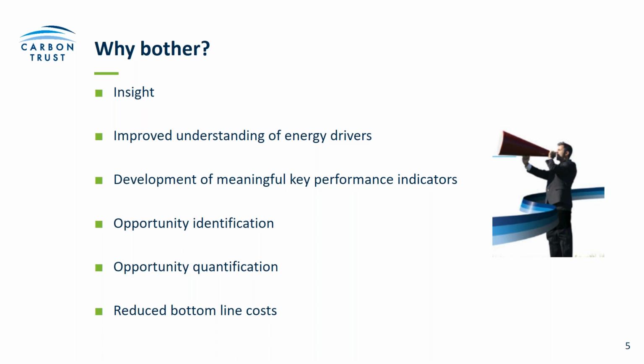The reason you would want to analyze your consumption data, in particular your half-hourly or quarter-hourly, is the insight that will give you into how and where energy has been used at the site. It helps you understand then what are the main energy drivers at the site, what causes you to use more energy or less energy.